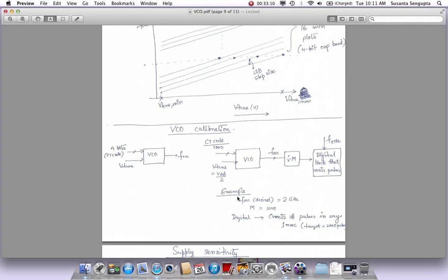So this is what is very important of the VCO calibration that we do in the beginning when the chip powers up, and we help it find an approximate solution by providing it a good approximate solution for the CT code. And afterwards we allow the whole PLL loop to come on and let it lock to the VTune value such that the VTune is actually closer to the usable range. We don't want to go towards these extreme ranges, right? We want it closer here, and that is the reason why we start from middle of the range, bring it closer, and then let it deviate a little bit here or there based on which is the frequency code and what is the corresponding VTune it finds to lock to that.